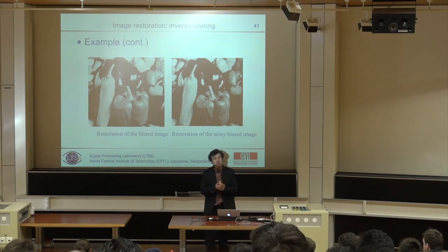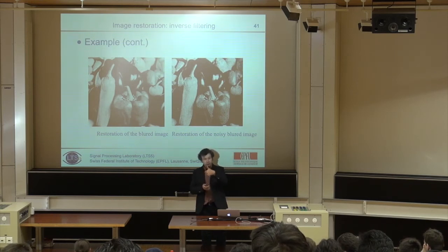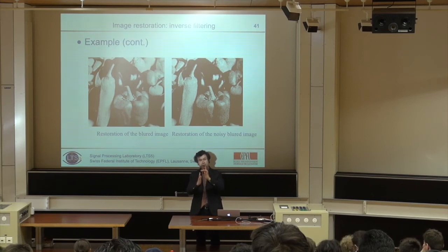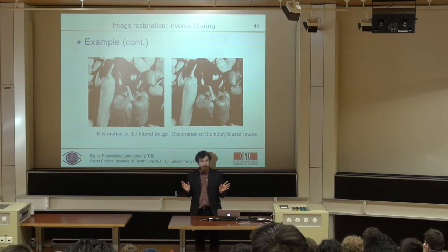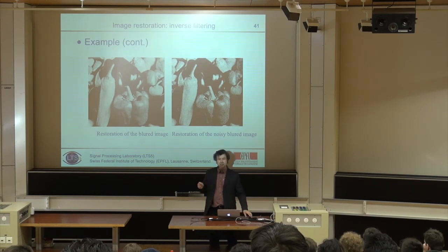But on the contrary, the inverse filter will be a bad idea at a given frequency if the power of the noise is much more than the power of the image. Then what you will have is basically an amplification of the noise and a marginal restoration. Or a good restoration, but hidden in a huge noise. You see that? So, what is the ideal solution now?